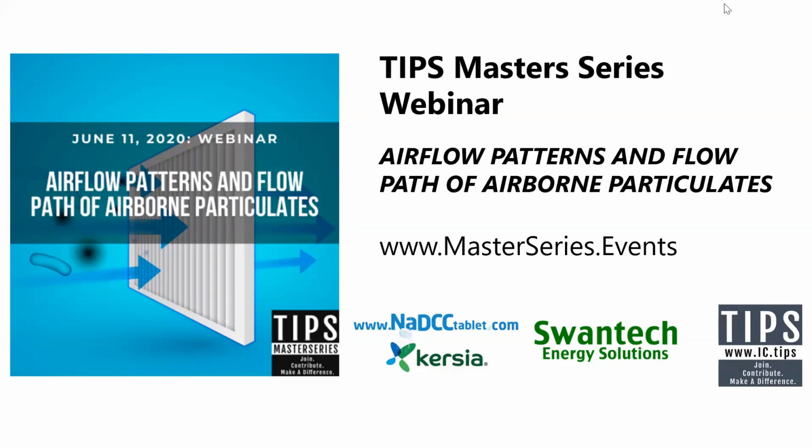If you have a very deep floor plate, more than 15 feet, remember that air that's coming in is not going to go away right away. It will take some circulation and wander in your space before it gets out. So again, the CFD analysis is not just limited to mechanically ventilated spaces. We can do simulations, and I have done several of those for naturally ventilated spaces.